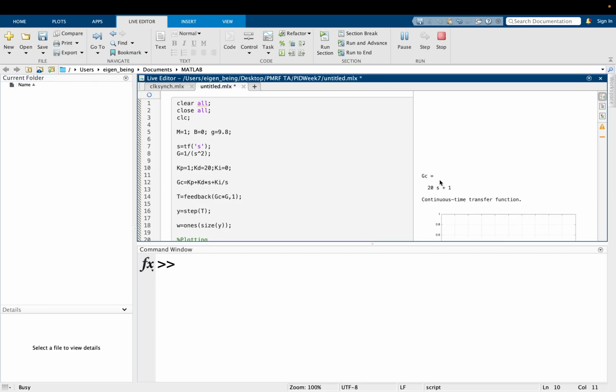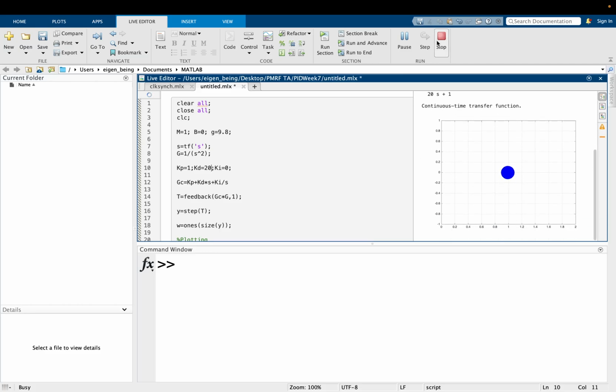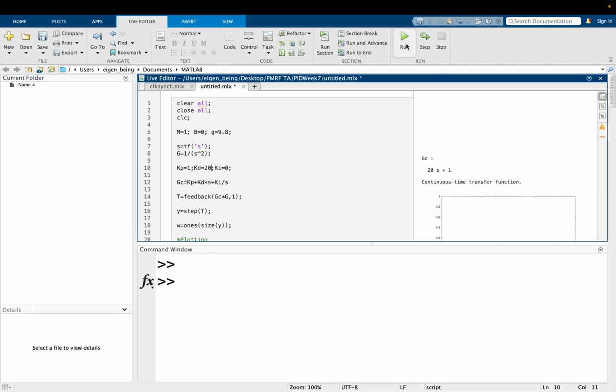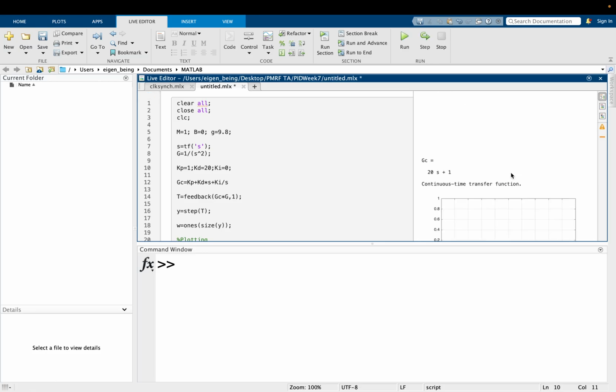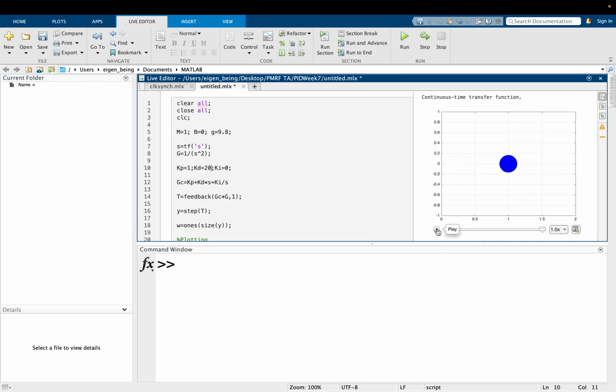Okay, I think you missed that animation. So if you see here, there is no overshoot. It's slowly, just like how you stop at a traffic signal, it just stopped. There was no overshoot. See, I'll just run that again. So it just stopped. This is how you should properly stop. And there was no steady state error. Why? Because the system was a double integrator system.